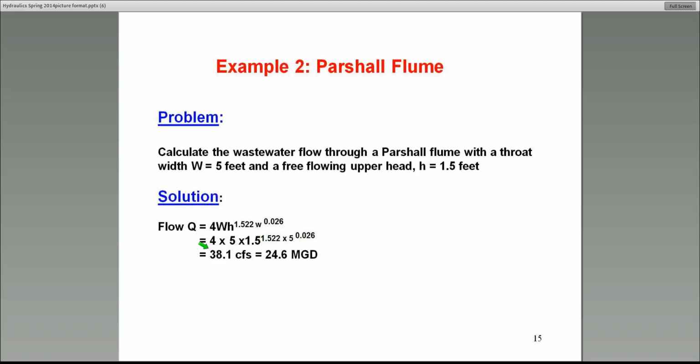That's a consistent unit. Typically in wastewater systems, we use a unit called MGD, million gallons per day. For those who do not know the conversion factor, I suggest you take one with you. I can tell you right now what it is. 1 MGD is 1.55 CFS. So if you want to make a note of it, that's fine. Million gallons per day is a preferred unit of measurement in water supply and wastewater systems.